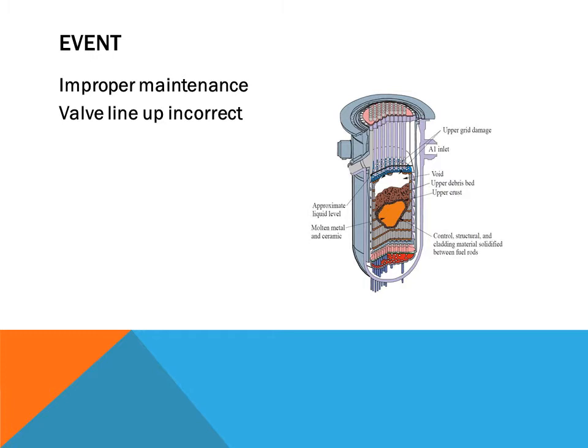Once the event happened, just a quick timeline. Feed water was tripped offline. Within 2 minutes, temperature in the primary rose excessively. This increase in temperature caused expansion in the water, so the level in the pressurizer increased. This in turn compressed the bubble at the top of the pressurizer, which raised the pressure. It got to the set point of 2,255 pounds, lifting the primary relief valve we discussed earlier.